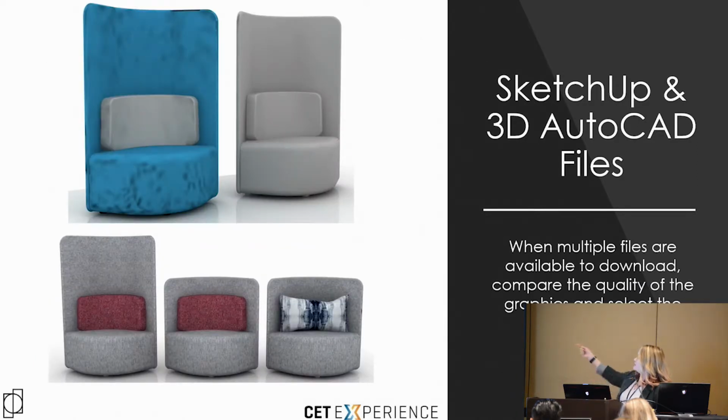So in this case, I downloaded both of those file types and put them side by side in CET. Then I do a very quick rendering of them exactly the way they are. I don't put any finishes on them, and I don't make any changes to them. I just do a very basic rendering, and I can quickly identify which graphic is the better quality. On the left-hand side, the blue chair, that was the SketchUp file that I downloaded.